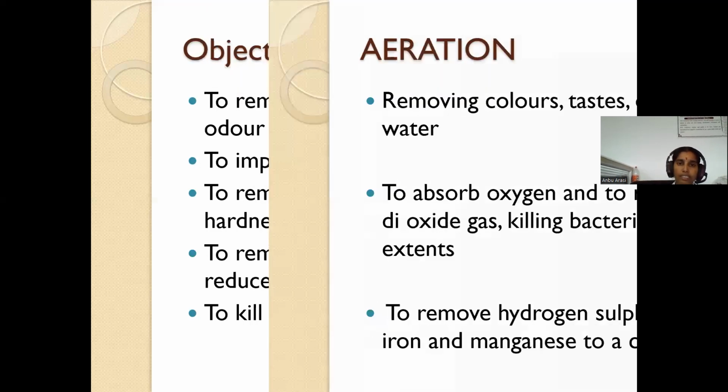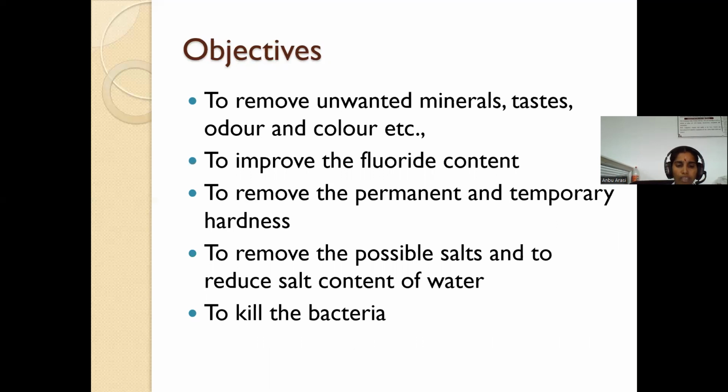Excessive fluoride content creates some dangerous effects, like affecting the nervous system and brain and causing cancer, changing lung structure and strength, causing birth defects and prenatal death, impairing the immune system, and causing initial stages of skeletal fluorosis and osteoarthritis. Similarly, dissolved gases like carbon dioxide and hydrogen sulfide cause bad odor and make the water a corrosive agent.